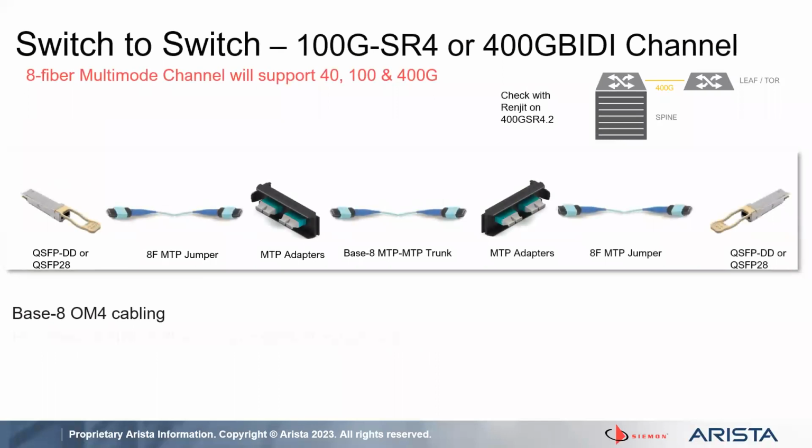So I'll take a look now at the multi-mode side. This is still switch to switch, and this is looking at 100 gig SR4, as I mentioned, or the 400 gig BiDi, the SR4.2. Those applications require an 8-fiber multi-mode MPO connection.